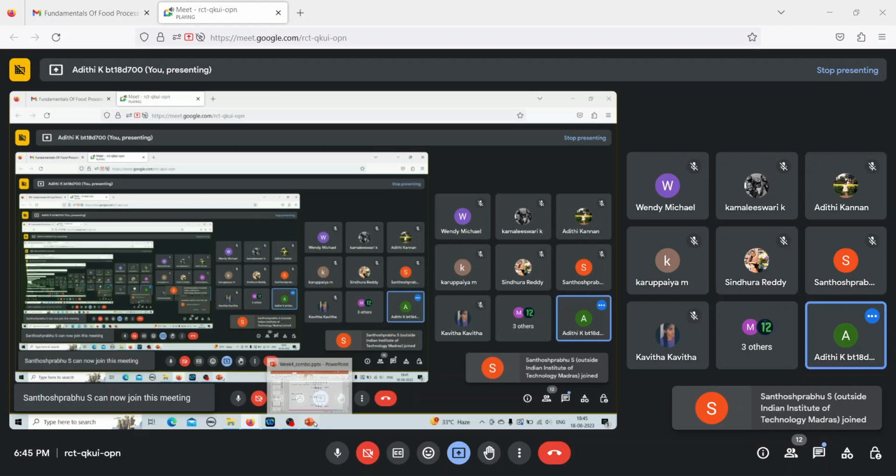We already know the mass flow rate of the vapor, which is equal to the evaporation rate. So the mass flow rate of the vapor coming out of the evaporator is equal to the evaporation rate, because if the evaporation rate increases, the vapor that you get will also increase. So m here is equal to 2000 kg per hour. Hi is given as 2625.3 kJ per kg.